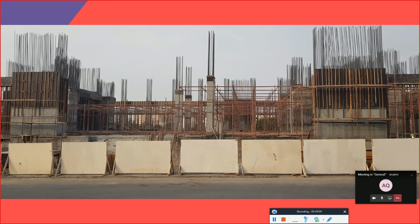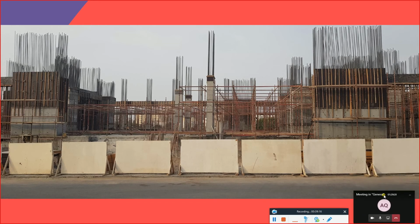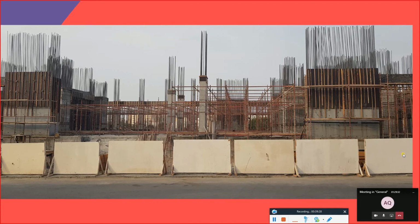Now after we have done our foundation, columns, and staircase, normally we'll go for the beam and slab. Why have we combined the beam and slab here? Because the beam and the slab are interrelated, we are doing the concreting for both of them together. So this is going to be the formwork for the slab.